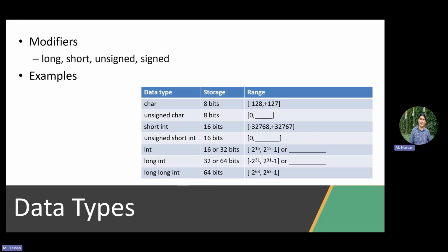More than this, it's not only about data types, but also modifiers of the data types. So it's not only about defining a character, for example, because a character is 8 bits. But what if you are indexing a register? Generally, an 8-bit character allows both signed and unsigned values, right? So if you have 8 bits, you go simply from negative 128 to positive 127. But if you're indexing a register, you will never expect an index to be negative. So it's more efficient to have all your 8 bits dedicated to positive numbers to enable a higher range. How do we do this? That's unsigned. Defining an unsigned character allows you, using the exact same number of bits in memory, to go from 0 to 255. So you doubled your range for your indexing without losing any extra bit in memory.